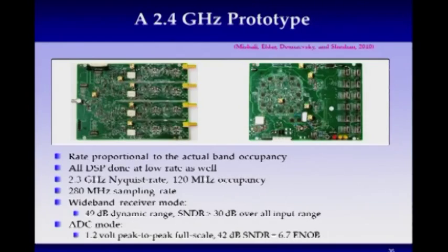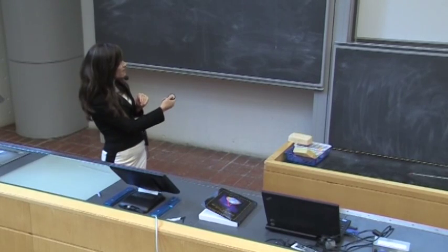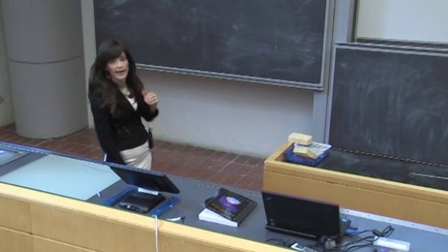So what you see over here are 4 branches. These guys are the multipliers. And this over here is a digital signal that we create as our periodic function. So our periodic function is just a bit flip sequence. This creates the bit flip sequence, and then you see over here there's 4 outputs that just go into each one of these modulators. So it's the same signal with different shifts that are input into this analog structure. And that's it. And this is the filtering, and at the output what you're going to get is that alias data.